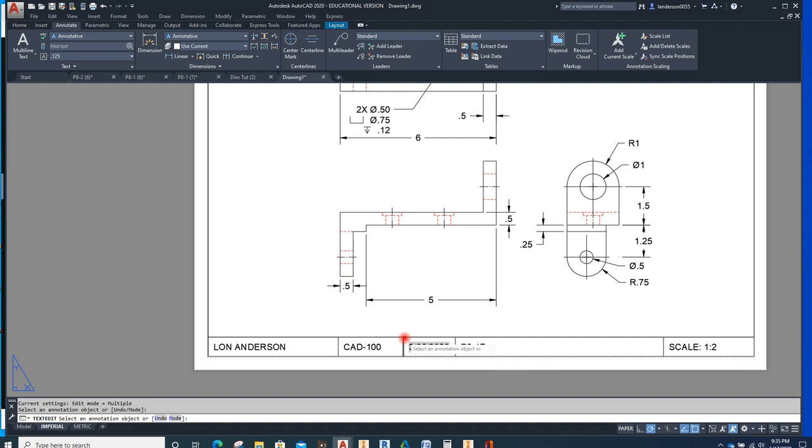And then if you set your title block up as I've got as I show in the video, you can type, let's see, UPDATE, update field. Click on that, hit enter, and there's today's date, 5/17/20. Matches what's down here, 5/17/20.